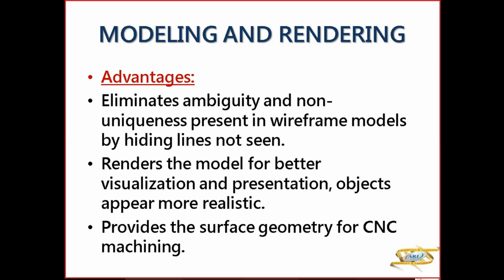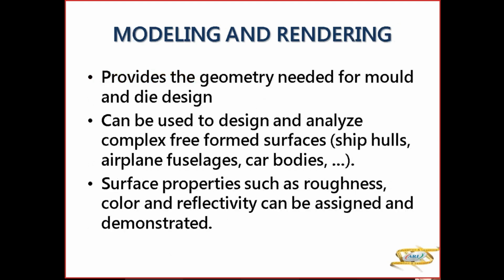Plus the rendering is better. I'll explain after this solid modeling what is rendering. Rendering is basically when your model has better visualization. You have the shading effect, so you get a better 3D model. You get a better presentation and make it more realistic. So the surface modeling is more realistic as compared to wireframe modeling. Plus you get a surface geometry for machining, and you can also do mold and die design with the surface modeling. You can also analyze your ship's hull or airplane fuselages or the car body with the surfaces.